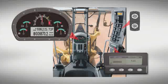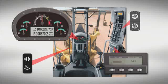The manual disable regeneration switch is found on the switch panel located on the right-hand cab post. On the front panel below the instrument cluster are the DPF lamp and Regen Active lamp.